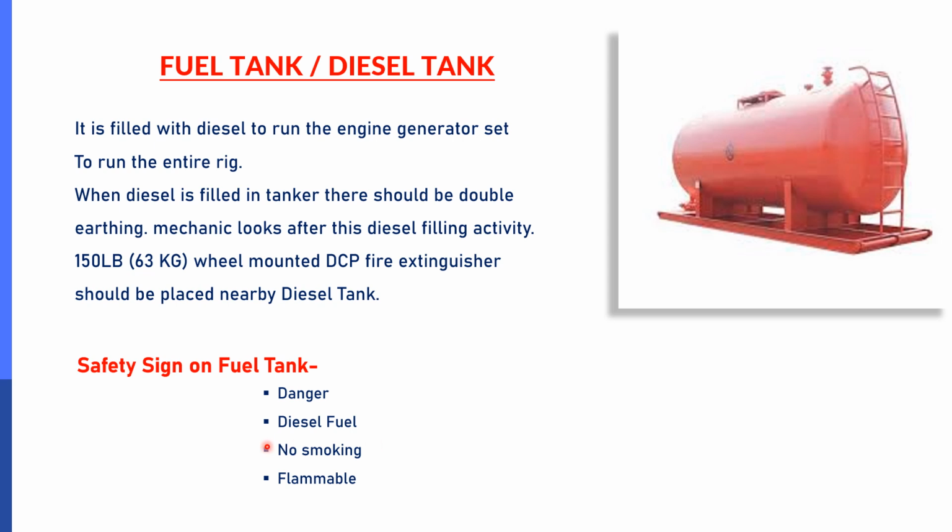That's why the diesel fuel signage should be outside of this tank. Then no smoking signage and flammable. This safety signage should be on all four sides of the diesel tank.